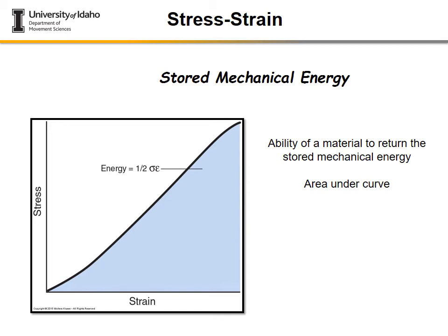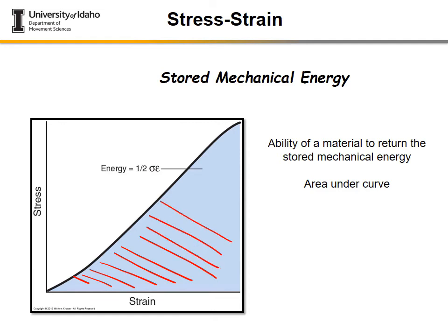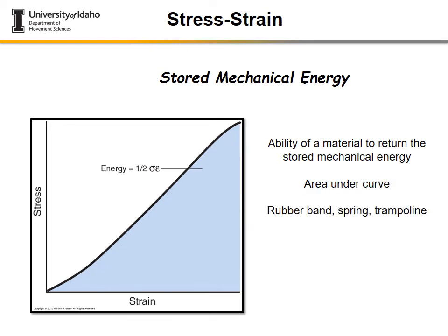So as you're compressing or applying a tensile force to it, the energy underneath this curve, and that black line right there is the stress-strain relationship, that's the curve. This blue shaded region is going to be the stored mechanical energy, and it's calculated as 1/2 the stress times the strain. So it is that area under the curve that we are going to be talking about. As something is loaded, we can calculate based on that what we expect the energy return to be.